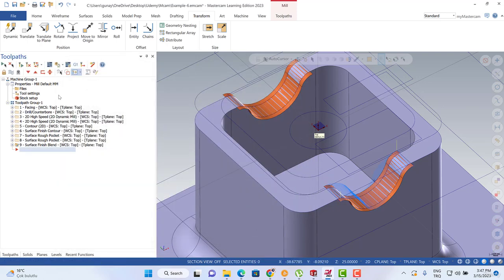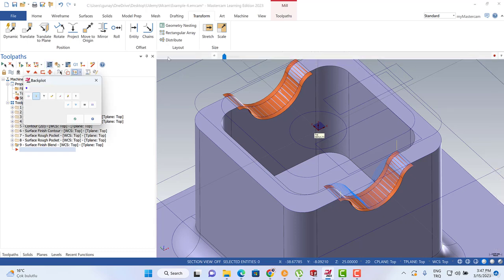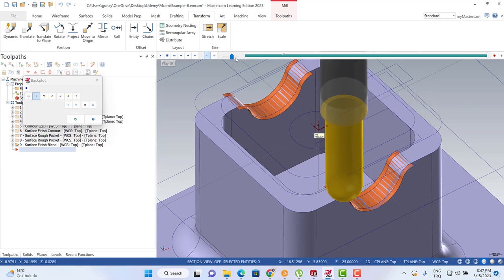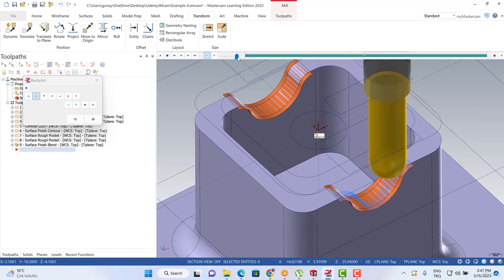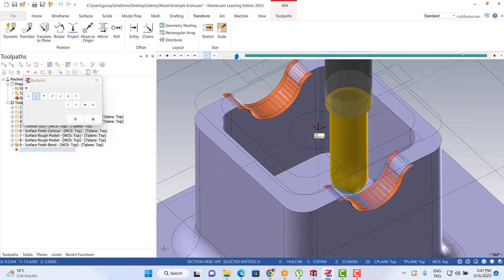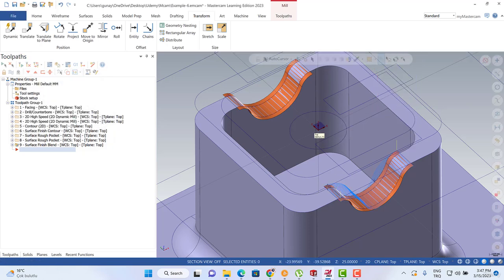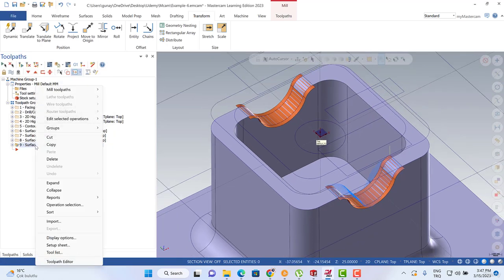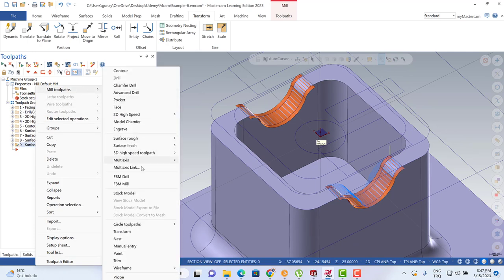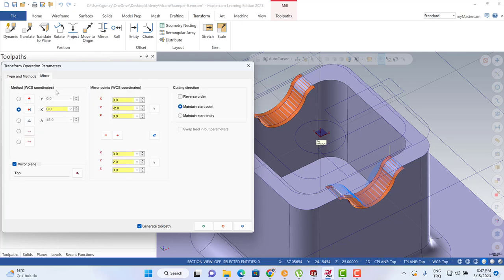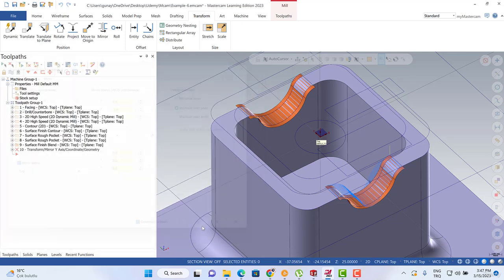And then we're gonna see that kind of toolpath for our finishing process. That is the perfect toolpath. Okay, that's fine. And after that, it's also possible to create this one. So this part, let me turn back to the mill toolpath and transform options, and we can select this one and the mirror options, and then we can select here, and then we can recalculate our toolpath.